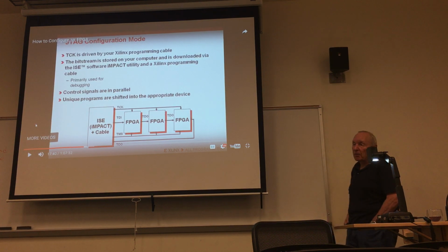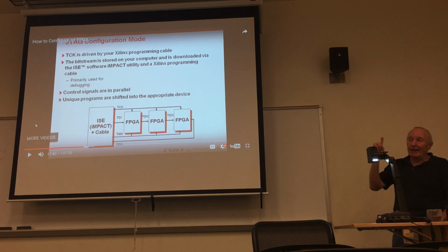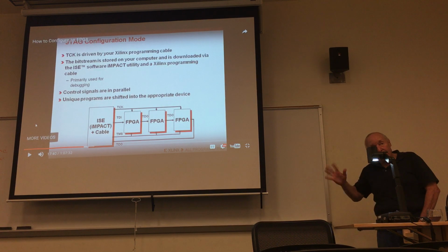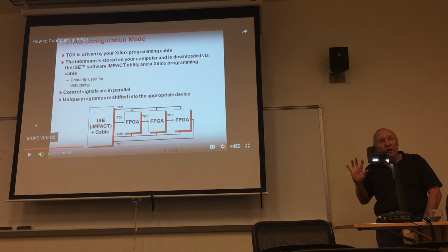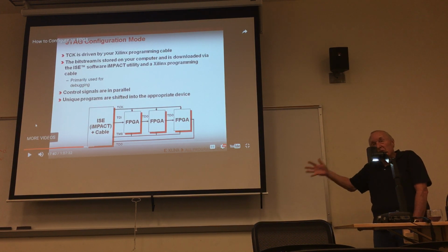So you always need to provide a JTAG interface on any board that's got an FPGA on it. That's a given that you do that. It's not costing you anything, it's only 4 lines. There's no additional circuitry required, so it's only 4 traces on your printed circuit.